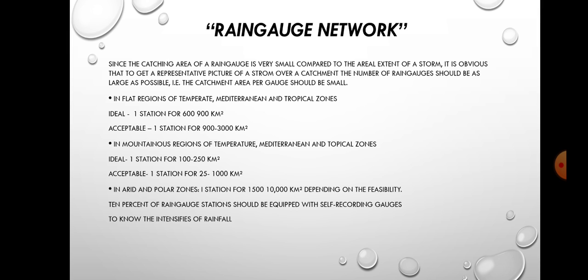In flat regions of temperate, Mediterranean and tropical zones, ideal is 1 station for 600 to 900 km squared, acceptable is 1 station for 900 to 3000 km squared.